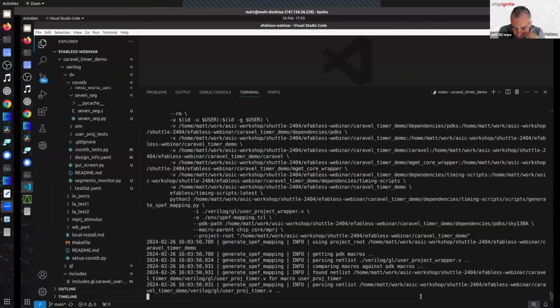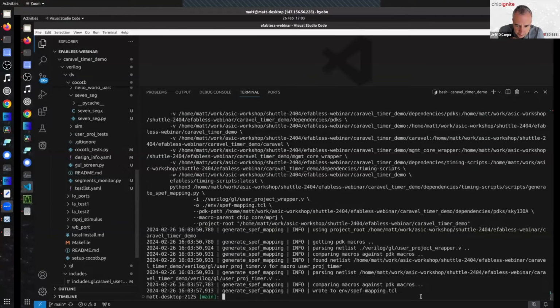Just along those lines, there are some common mistakes in terms of hooking up. There's a 3-wire interface for the IOs, right? There's an input and output and an enable line, and those need to be configured correctly to propagate your signal out the pad, and simulation will obviously confirm whether that was done correctly or not. That is a common mistake we've seen in previous designs, where someone didn't connect those correctly. We are putting additional checks in place, which I don't know if Matt's going to cover, pre-check or some of the further steps to help identify those. But that's part of the reason for doing that simulation on the chip.